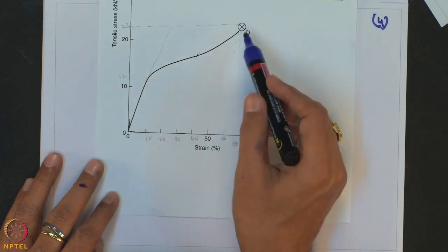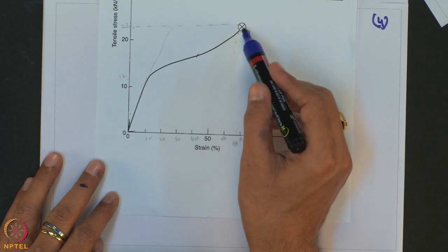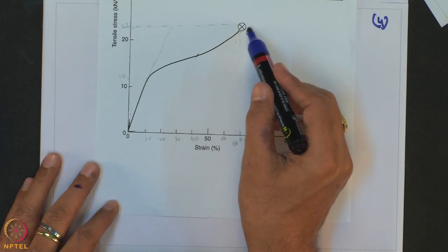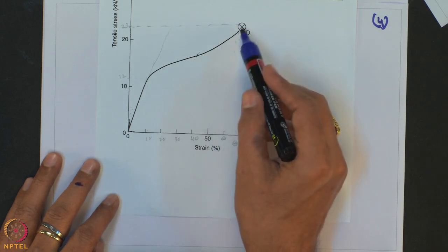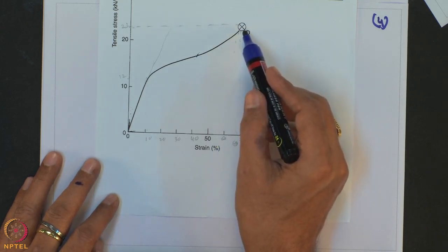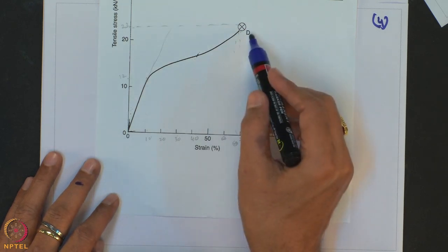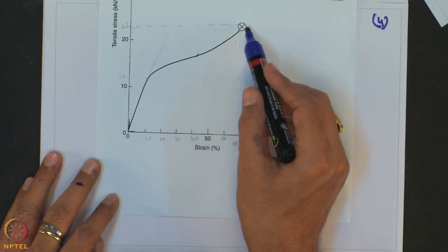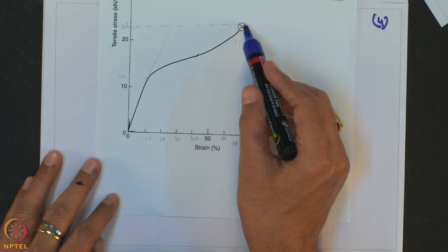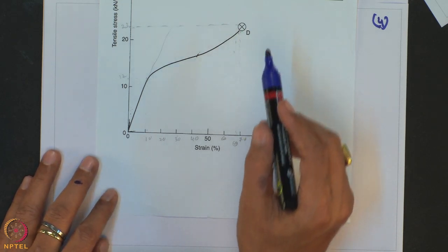For example, this is a non-woven heat bonded material, and its mass per unit area is 135 gram per meter square, and the thickness of this non-woven heat bonded geotextile material is 0.33 millimeter.